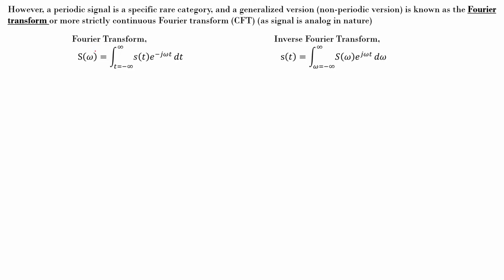Okay, so that's it. Then you change to another omega 0 and do the same operation. So you vary omega from minus infinity to plus infinity. For each omega, you find the S of omega value. And then if you plot the magnitude of that, so this is omega, of course it goes from minus infinity to plus infinity. For each of these omega, you plot the magnitude values, something like this. That is what you get in the Fourier transform.